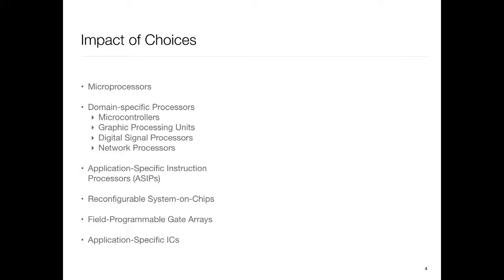So what you would find in DSPs is they would have the ability to operate on vectors, but the key measure that they would go after is whether they could do multiply, accumulate very rapidly. So you'll find in DSPs a MAC instruction, okay, single cycle multiply, accumulate. Then you would find accelerators or specialized units for doing FFT, indeed, because what happens in FFT? How can you speed up FFT? Anyone remembers? When you access the array on which you are doing the FFT, how do you access it?